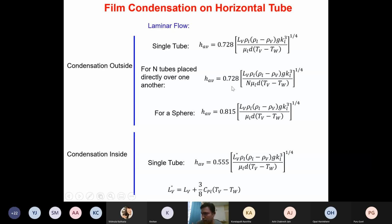Remember, if there are 100 tubes and you are having maybe 10 columns, each column will have 10 tubes over one another. So this N is going to be 10. It is not going to be 100. So don't get confused with this. This N is the tubes placed directly over one another.